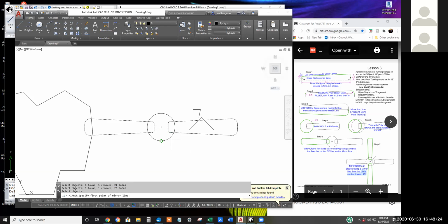Again, hover on the circumference makes it clear that you're looking at a circle. Polar track up any one of these diagonal 45-degree polar tracking lines. AutoCAD says specify second point. IntelliCAD says end point. Click anywhere on a polar tracking line going diagonal.